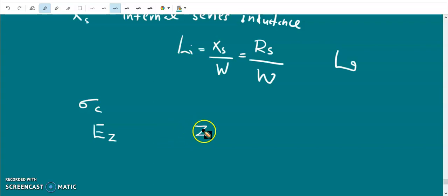So along the transmission line, the wave transmits along the z direction, and for the lossless transmission line, we have taken that the electric field is along the y direction and the magnetic field is along the x direction. But in the case of a lossy transmission line, in order to accommodate the averaging Poynting vector, we need a small axial electric field component. So this component shows that there is a component of electric field in the direction of propagation. So this shows that the wave transmitting along a lossy transmission line is not strictly transverse electromagnetic.